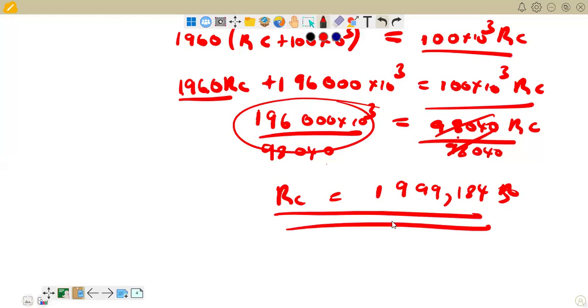All right. So now that we have it, let's go to the next question on calculating RB. Right. RB, we get it from the formula Zi, the input impedance that we've been given there, is equal to RB multiplied by Z1 over RB plus Z1. Fortunately enough, these formulas are given, they are there on the formula sheet. We are taking them from there. Right, but then we do not have Z1 there. So we need to calculate Z1 again.